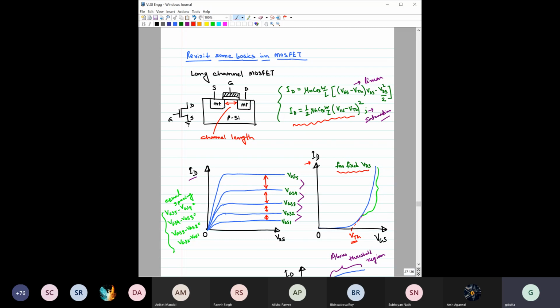Now, one minute. Right. So you are expected to get a quadratic line here, right? Okay. And so whenever you see a quadratic line, then you have understood that this particular transistor is being operated in the saturation region, right?